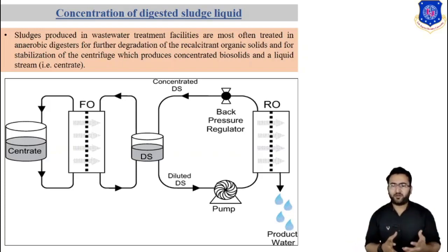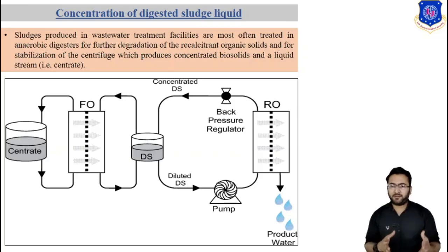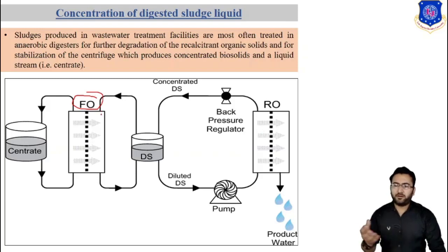However, the centrate is pre-treated by filtering it through a 150 mesh sieve. Water is then extracted from the pre-treated centrate using a cellulose triacetate membrane and NaCl draw solution. So for this, the forward osmosis process is used, where natural separation occurs due to the forward osmosis phenomenon.